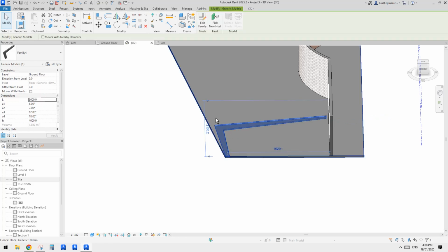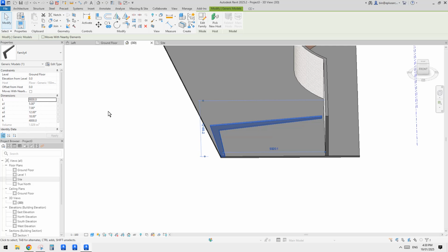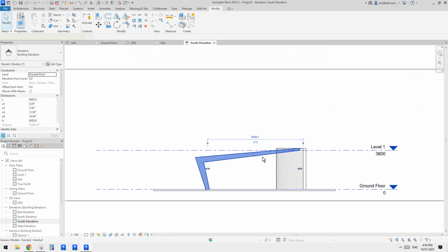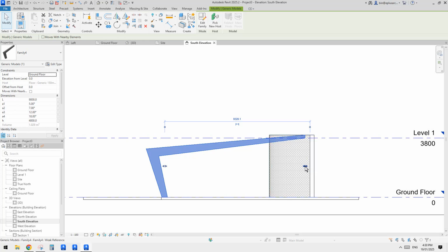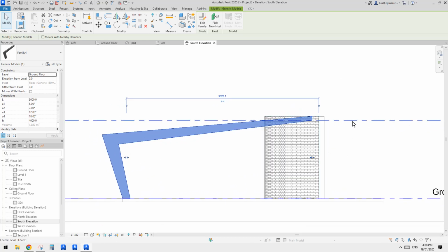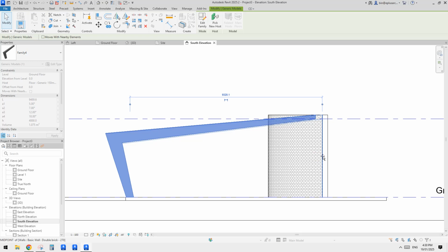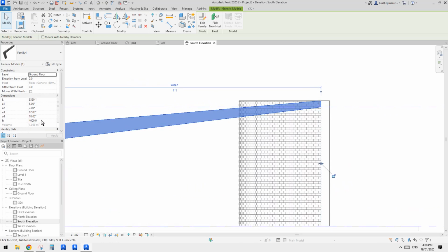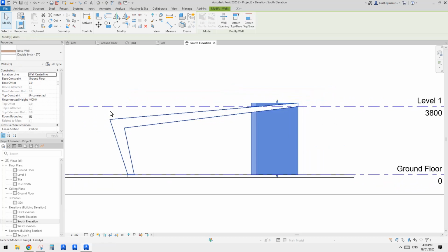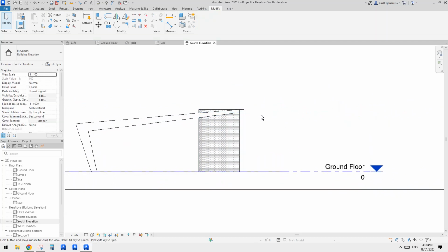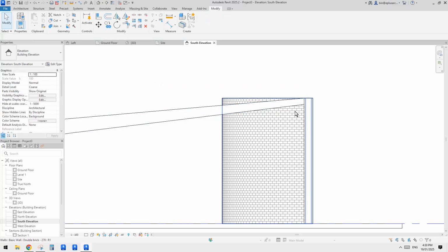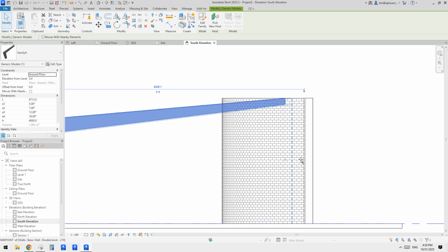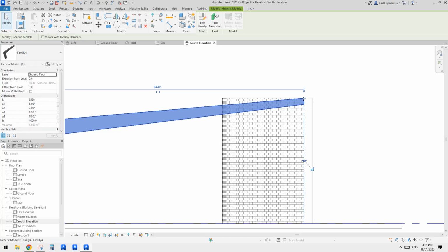So you go to parameter, so you can just change them, and you can also go to elevation, because we have this overall length parameter as instance parameter. It's easier to do it this way. So you can see, you can just drag this family, it will go here, and also you can see the height currently 4 meter matches this wall. So we have this wall at 4 meter. Just ignore this level. So it will automatically match. Doesn't matter where this one stops, it will always stay at 4 meter at this point.